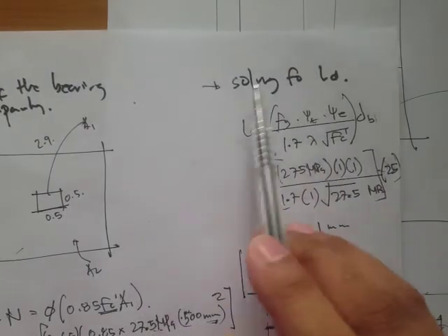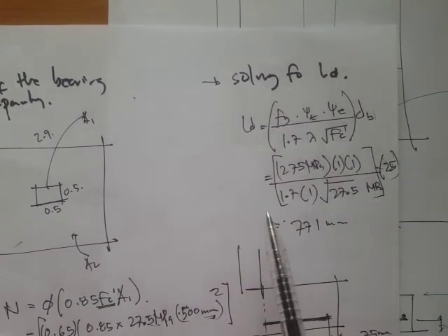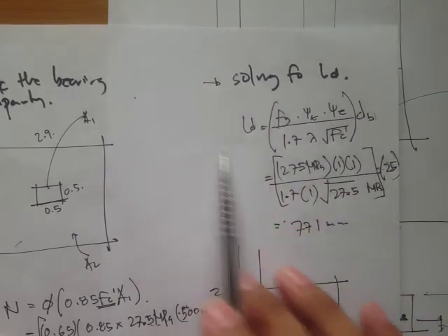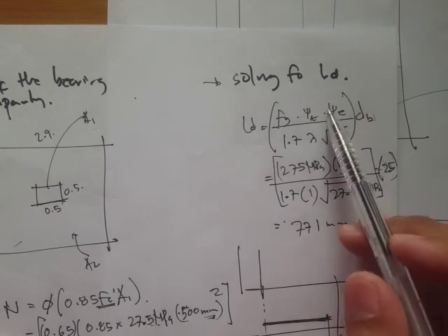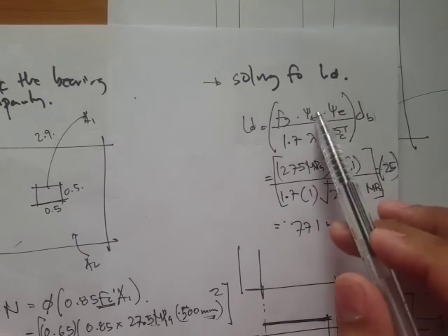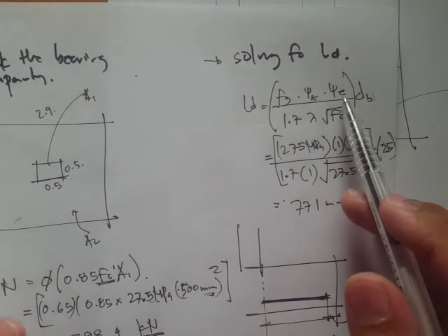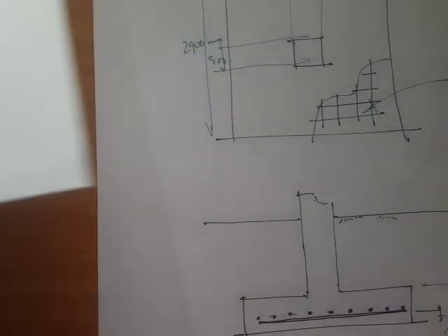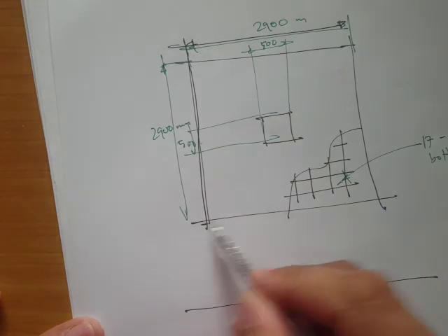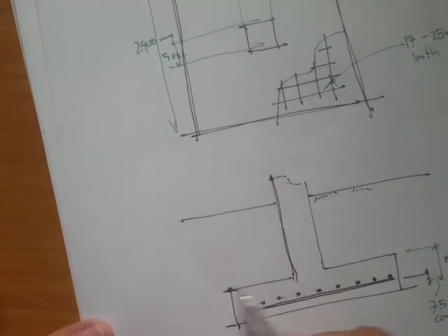Then the last is to solve for the development length. Now, since our bar is 25 mm and larger, then we have these equations. Now, as I've said, unless otherwise given, these coating factors and location factors, if they're not specified here, just use the value of 1. Okay, and finally, don't forget that you have to provide a summary on this footing design.